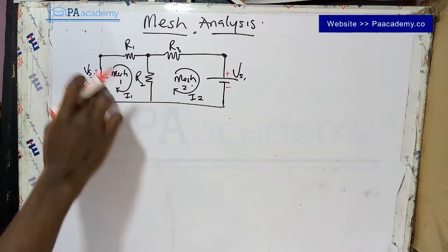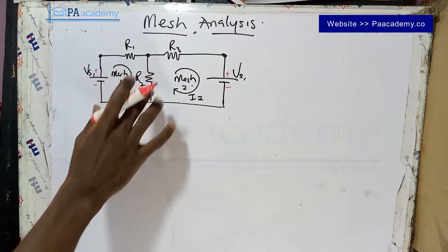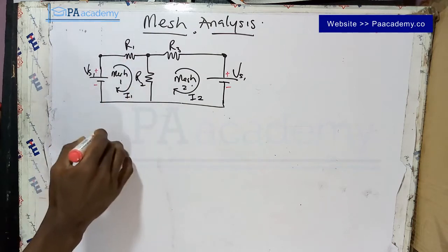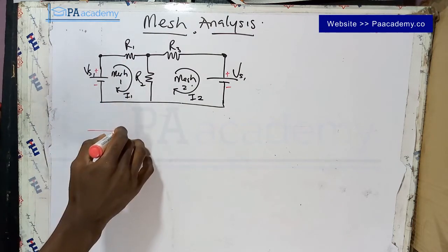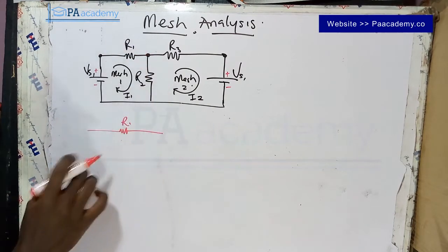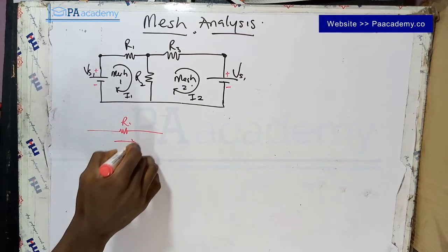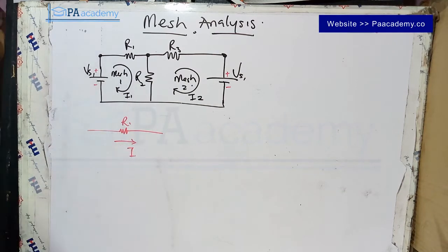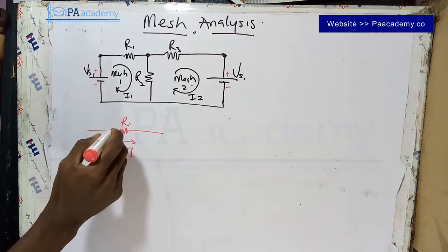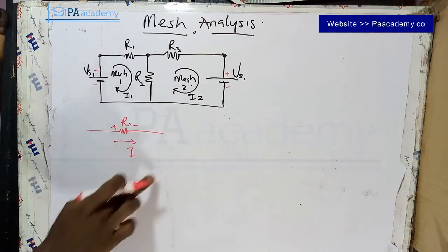Alright, so in a clockwise direction, remember that, let me also say it here, when you are dealing with Kirchhoff Voltage Law, if you are moving in clockwise direction across a particular element, let's say like this. So let's take this to be our R1, for example. Let's bring this out. If this is our R1, if our current direction is like this, that's the direction of our current. So that means the polarity that we are going to be having for this resistor is going to be plus to minus. That's because it is going in this direction.